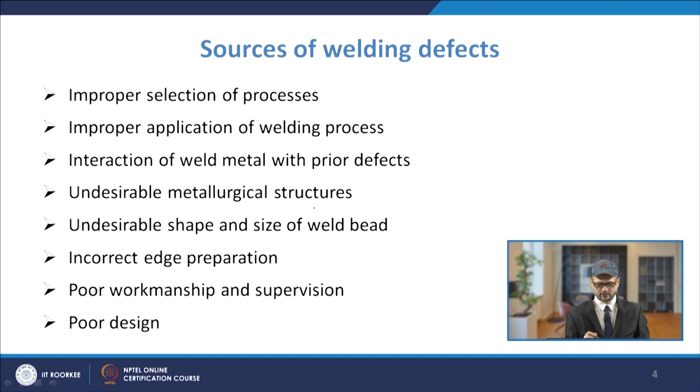You may also have undesirable macrostructural or metallurgical structures because of inclusions such as tungsten oxide or slags. These inclusions are detrimental for the quality of the weld.